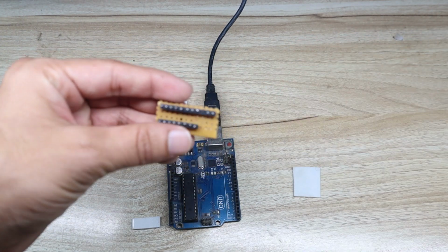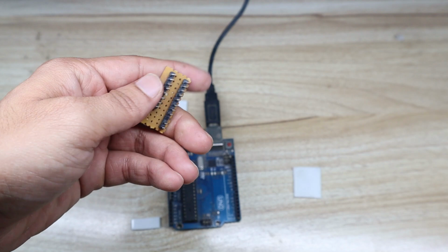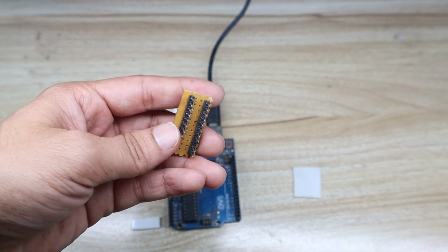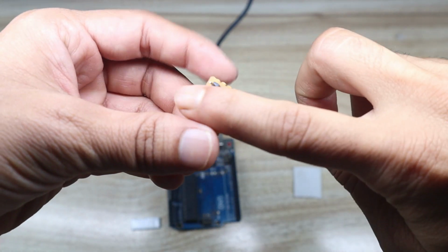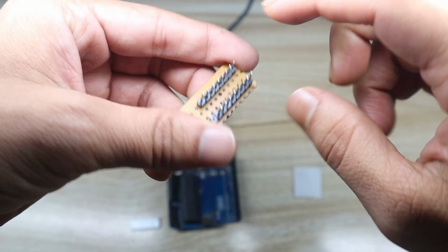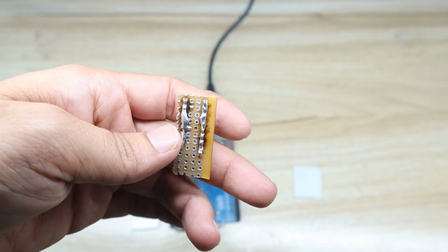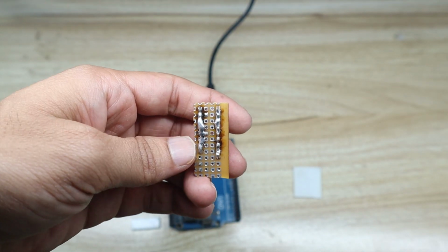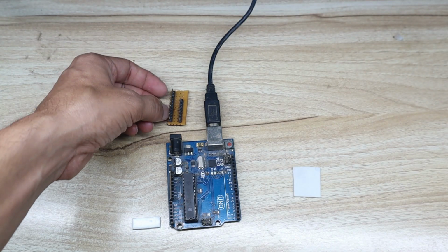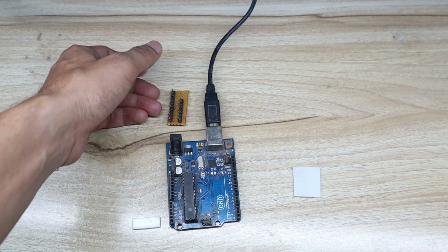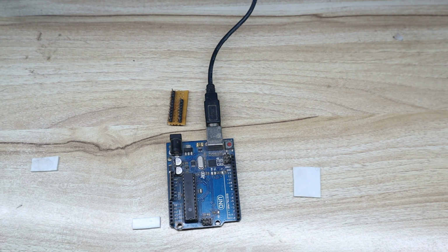Then after that you can see this is a simple circuit. You can use a breadboard, there is no issue. This is just a common VCC, common ground circuit. You can see a zero PCB with some connector pins and strips, and I have just shorted that strip here vertically. I use this whenever I need ground, because I need many ground supply pins for my sensors. That's why I use the common ground, common VCC circuit here.